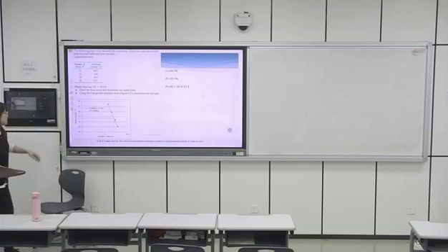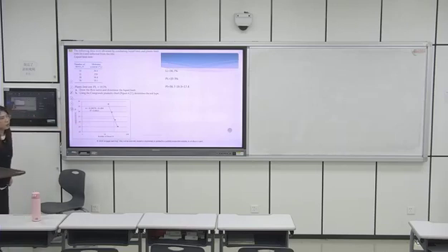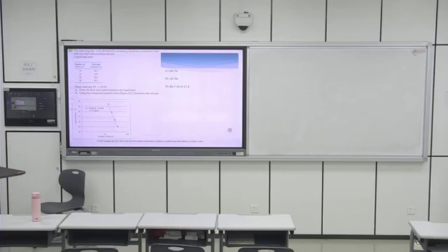So this is the definition for the liquid limit test. For the percussion cup, you need to find the water content corresponding to 25 blows. Okay? And the x-axis must be in log scale. So then you find the liquid limit right in here. It is 36.7%.